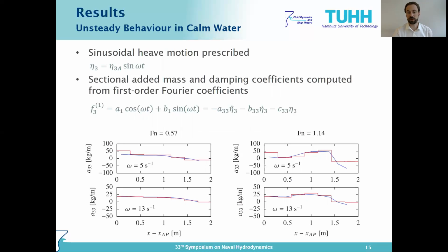From the simulation, we then get time histories at Earth-fixed cross planes rather than ship-fixed cross sections. So we obtained the histories of the vertical forces at ship-fixed cross sections by linear interpolating from the results of the Earth-fixed cross sections.